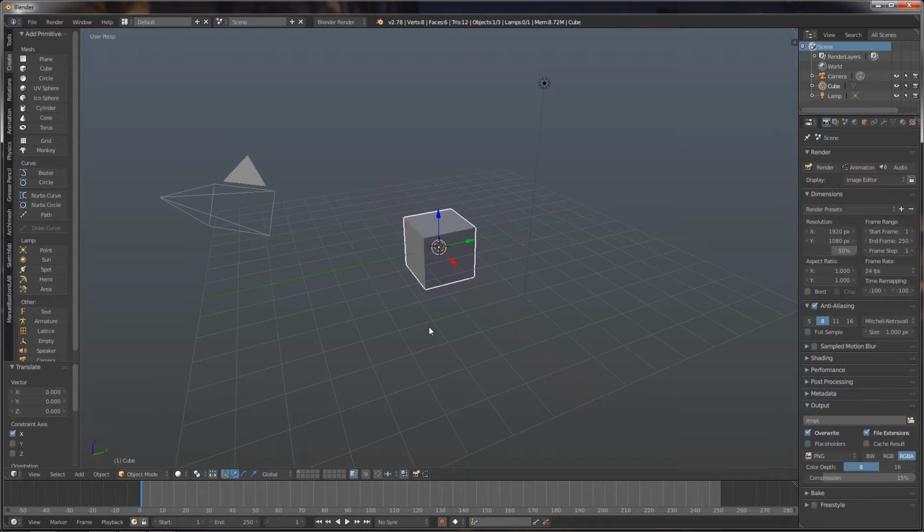The best and easiest way to start modeling in Blender is to simply start with a primitive mesh and then reshape it, add detail, and turn it into the model you want. In order to edit any object, including primitives, you will need to go into the Edit mode in Blender. By default, we are in the Object mode, where we can select the actual objects in the scene. If we want to make changes to the cube, we need to right-click on the cube to select it if it's not already selected, and then go into Edit mode by using the Tab key.